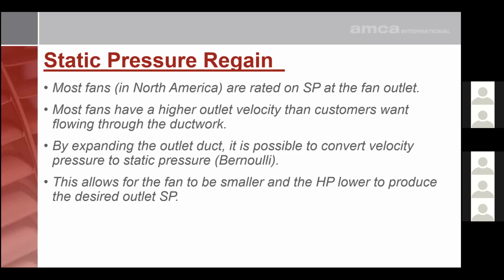And so regain lets the flow expand and slow down, and some of the velocity pressure gets converted to static pressure so that it can do useful work through the system. Most fans in North America are rated on static pressure.